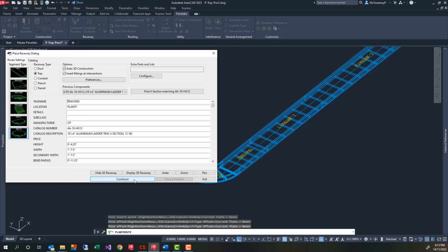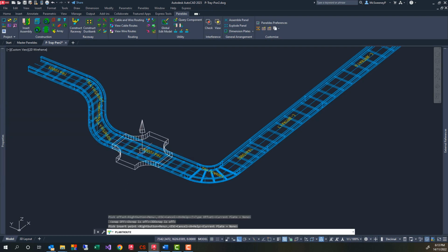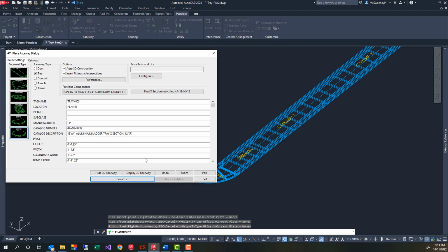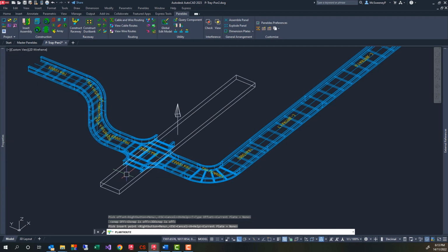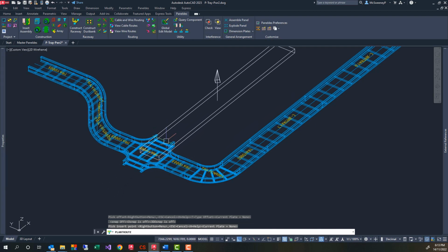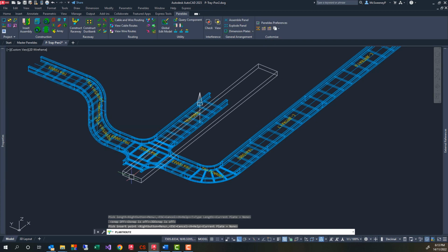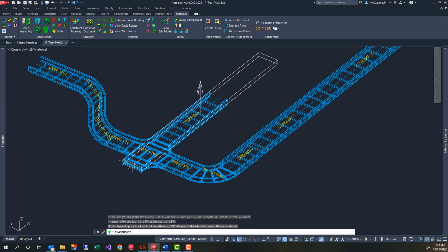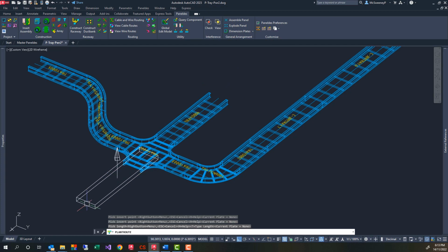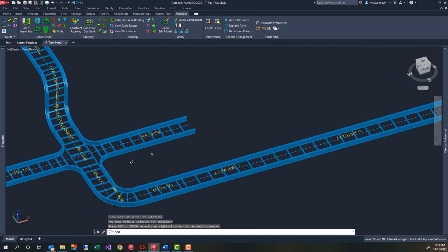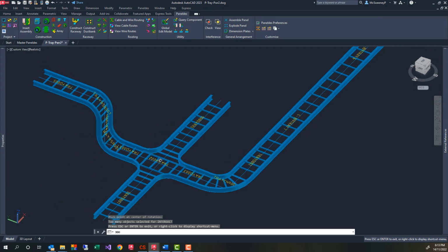I will now find and insert an X-section fitting that I can use with the existing linear tray. Paneldes breaks the fitting into the linear tray and renames the residual short trays. Obviously, I can extend my Raceway network from this fitting with the same methods. The fittings available in Paneldes include corners at most standard angles, inside and outside risers, T's, Y's, X's, and both offset and centered reducers. I will now demonstrate a second method to create new Raceway.